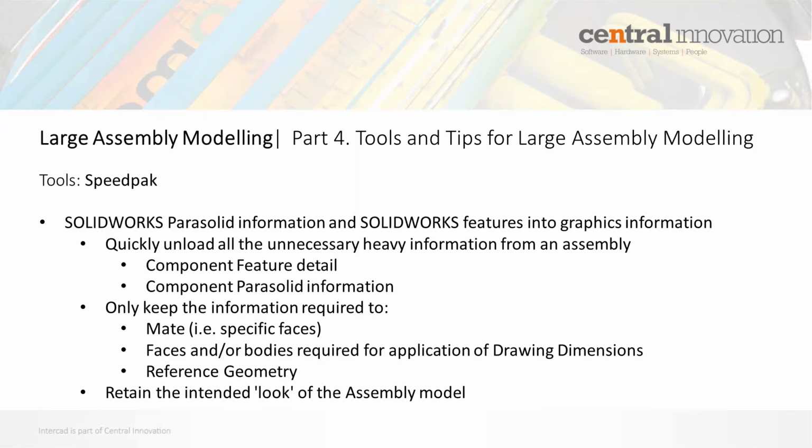It only keeps the information required to mate, so some specific solid information is retained where you need mated faces, and faces and or bodies required for the application of drawing dimensions. So you can specify faces or bodies that you require in the drawing that you need to reference from, and any reference geometry.